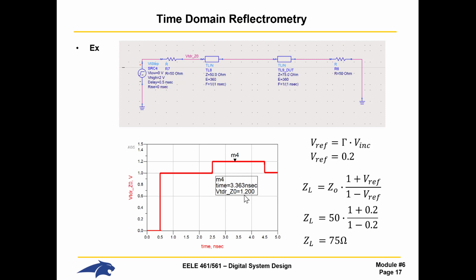Now, which of that is reflected? Which of it was there? Well, we know what was there because it's 1 volt. So here's 1 volt. So then the reflected voltage, which is superimposed onto that at this node right here, is 200 millivolts. And that is due solely to the impedance discontinuity between 50 ohms and here. And what's neat is this 50 ohm delay right here. It doesn't matter whether it's 100 picoseconds or 10 nanoseconds. There's no impedance discontinuity until you get to your DUT, and then bing, you have a reflection. It travels back, and you see it, and that's it.